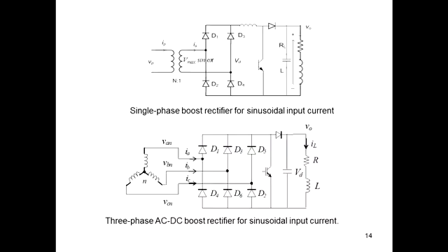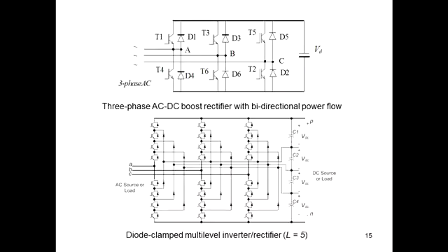Okay, now this is also the same circuit. Instead of single phase, it's a 3-phase bridge, and just using one boost converter, one can produce unity power factor here. All right. This circuit is not very much used nowadays, because if it is a 3-phase system, it is already quite substantial. It's not a very small generator. Okay, and this technique with a single switch is not very good in terms of performance of producing unity power factor. Okay, you still have quite a lot of harmonics in the input current. Okay, that's why we go for the other, right?